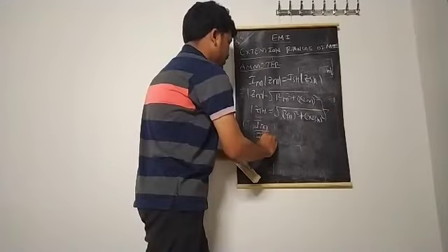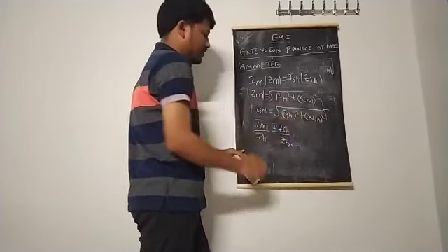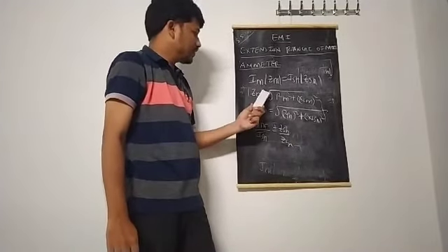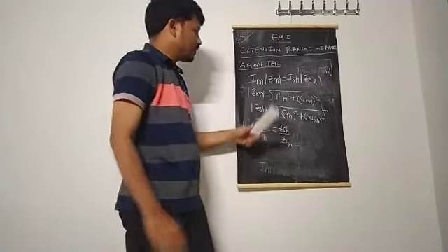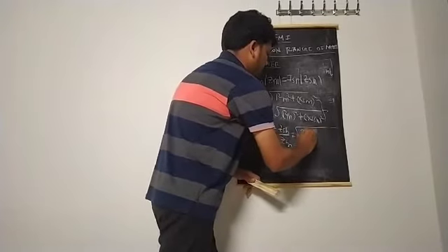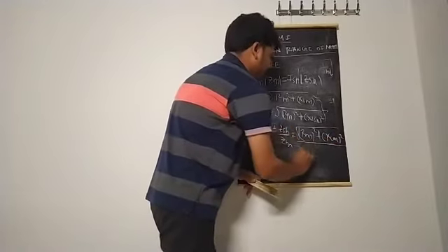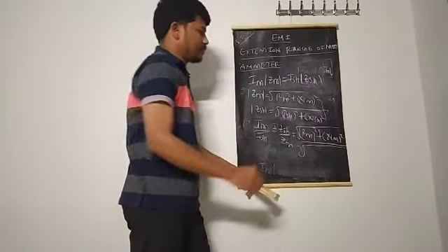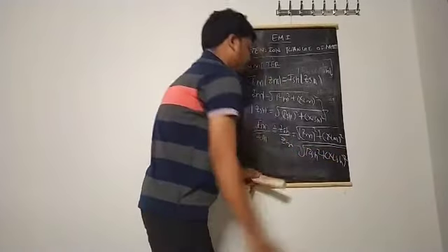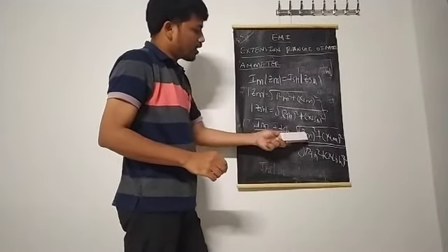Im by ISH is equal to ZSH by Zm. So from this, first let us write Im by ISH is equal to ZSH by Zm. What is ZSH? This is the equation. What is Zm? This equation. Substitute these above equations here. So from this we got square root of Rm square plus XLM whole square by square root of RSH square plus XLSH whole square. Is it right?